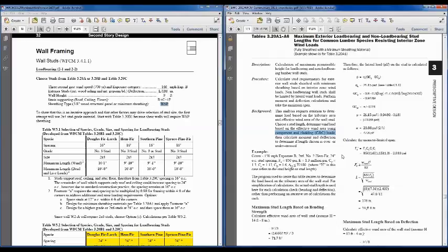But that, again, allows us to look solely at the bending loads on these studs, and those control over the combined bending and axial using main wind force loads for the scope of studs that we're designing in this wood frame construction manual. So that's an often overlooked assumption or interpretation, and I'll leave you to look further into that on your own to verify. But those are the assumptions underlying